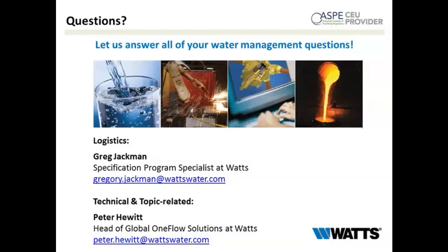Okay. Is there a minimum flow rate per unit of media? Flow rates are going to determine what size of system is recommended. So yes, liters of media are relevant to the size of the system, whether it's a cartridge-based system on the low end, 1 gallon to 10 gallons per minute flow rates. And obviously in commercial buildings, you could see flow rates from 100 to 1,000 GPM. So system design is predicated on understanding peak flow rates, continuous flow rates, occupancy rates of buildings on the commercial side, and water usage on the residential side. So there are variables to consider.